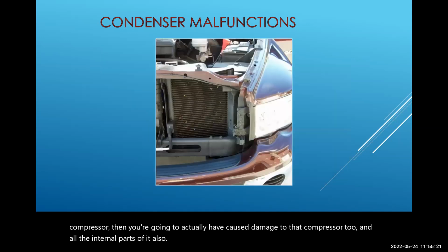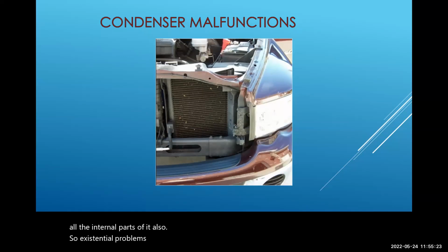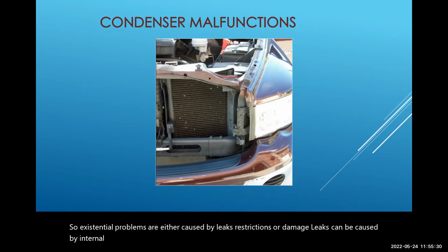Condenser problems are caused by leaks, restrictions, or damage. Leaks can be caused by internal or external corrosion from road salts and other environmental pollutants. Leaks can also be caused by loose or broken mounting hardware.